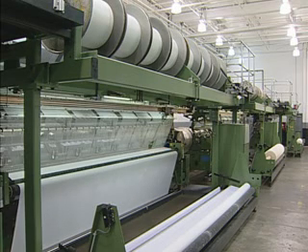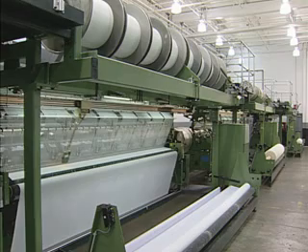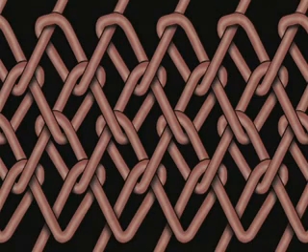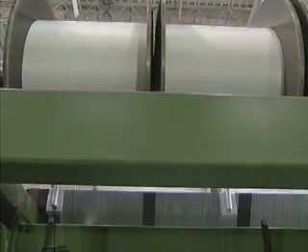The second system used for knitting is known as warp knitting. These machines are designed differently in that they form the knitted loops from yarn in a vertical direction. This illustration shows how warp knitting, in contrast to weft knitting, is accomplished. Looking closely at the illustration of a warp knit, it can be seen that the yarn is intermeshed vertically over 2 adjacent wales. These warp yarns are fed vertically and parallel to the direction of the fabric formation.